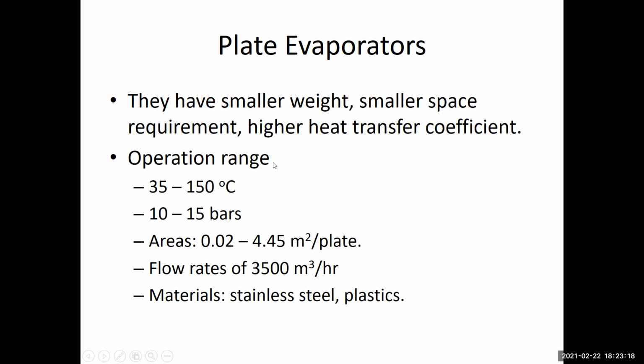The operation range of the plate evaporators is something like between 35 to 150 degrees centigrade for pressures of 10 to 15 bars, and the areas are actually modular, so you can add more plates so the area increases, and they support high flow rates of the fluid in.